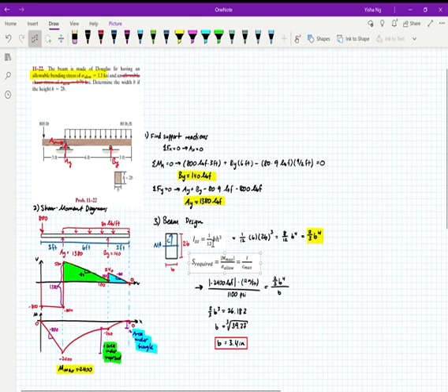So based on this equation for rectangular moment of inertia, I'm going to plug in my values for B and H and calculate that out, and I get that I is equal to 2/3 B to the 4th. Okay, so I'm going to take that number, I'm going to plug it into this equation. I know my M max, I'm going to take the absolute value of it. Once again, I'm going to convert from feet into inches because my units here were feet. I know my sigma allow is 1.1 KSI. I'm going to convert that into PSI, so I'm multiplying by 1,000 here to get 1,100 PSI.